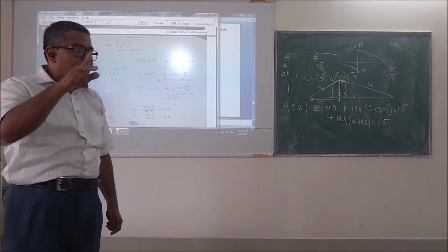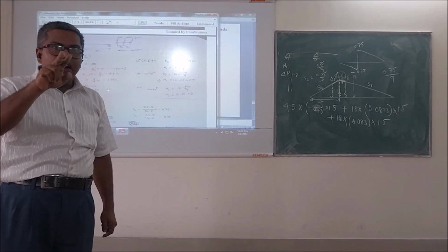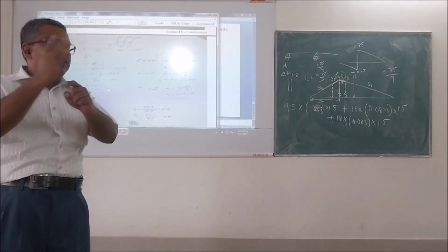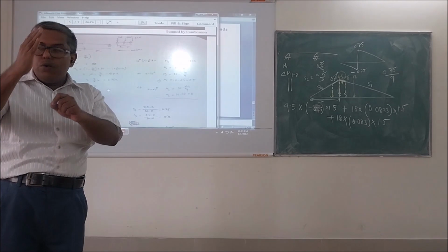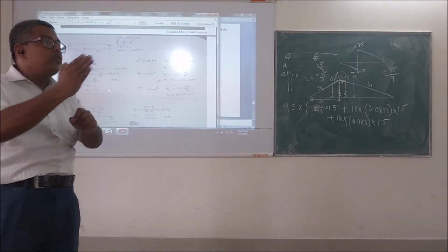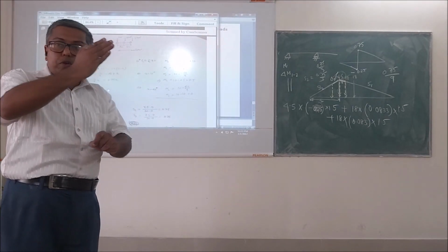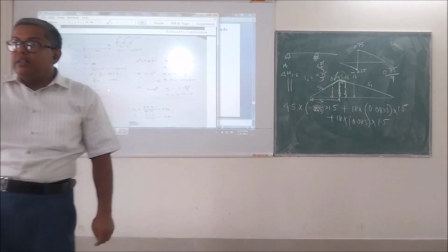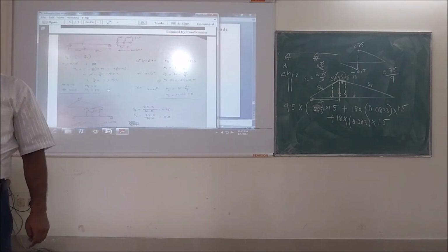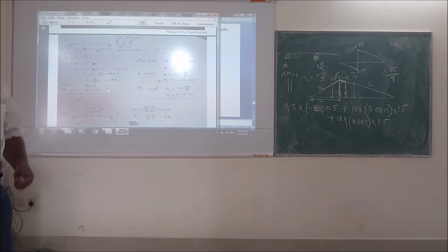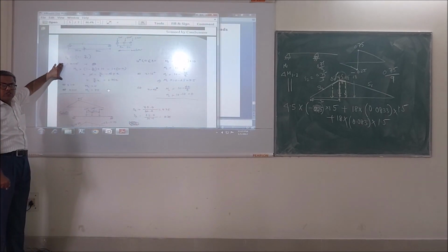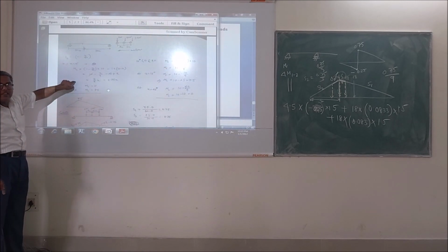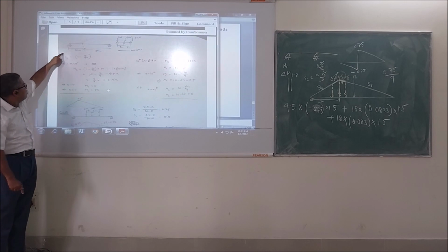The position of the load depends on how you are positioning the load, not how you are moving the load. So you will have to position the concentrated load at the maximum coordinate position. If I am not getting into the influence line diagram construction, you will be able to see here why we are getting a straight line, correct? So this is how we do it.